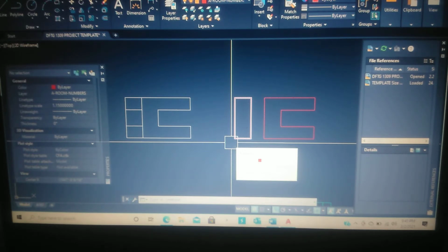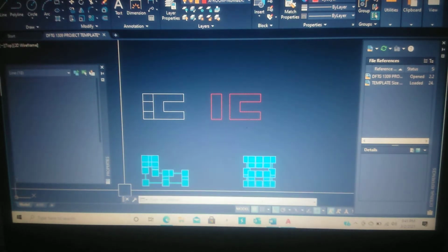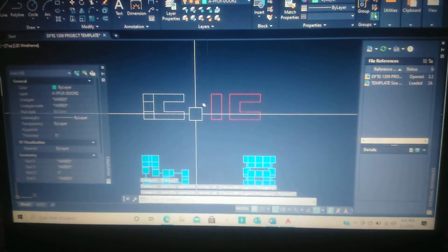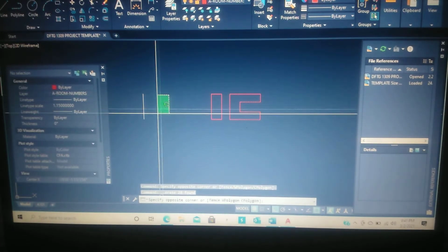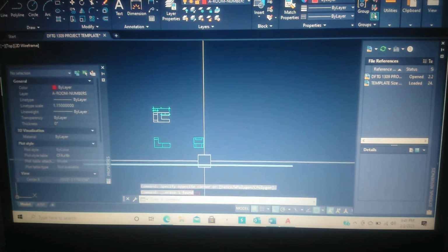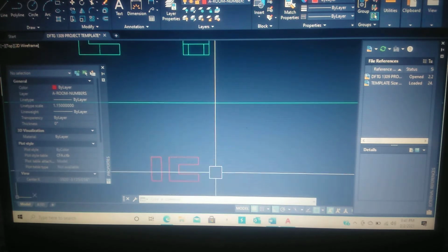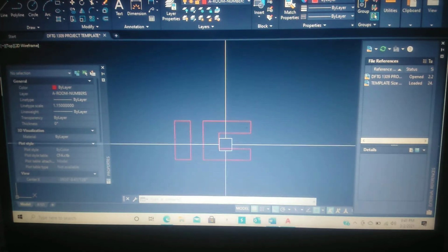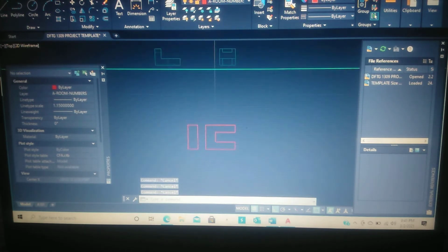All right, so first thing we want to do is, now that we have that drawn, let's go ahead and just delete these because we don't need them anymore. I just like to copy things down when you're doing 3D because in most cases you're going to be drawing polylines over what's drawn in 2D and extruding them. So once you have these two drawn, you would come here, hold down Shift, and you see the scroll button on the mouse?